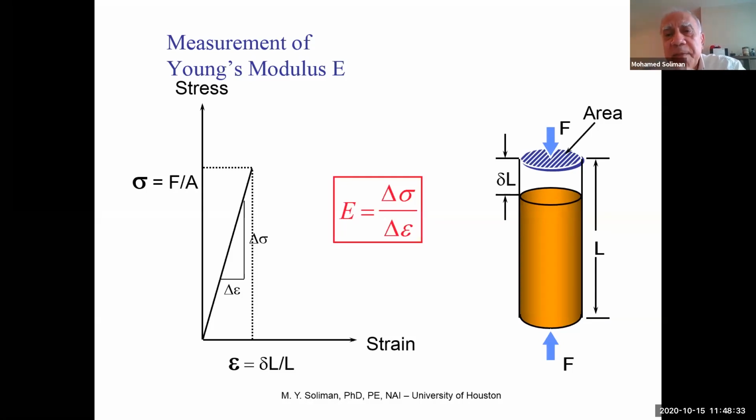In the lab, I get a plug or a core, and apply stress. I keep varying that stress, the force. I increase the force, so I'm increasing the stress. Then I take the change in height of that plug and divide it by the total length.